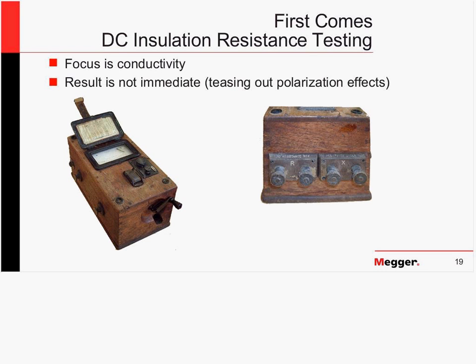In fact, you've probably heard of the PI test, polarization index test, where you're comparing your resistance value after 10 minutes to 1 minute, and you don't expect them to be the same because you're still waiting for some of these polarization effects to get teased out. So that was what came first.